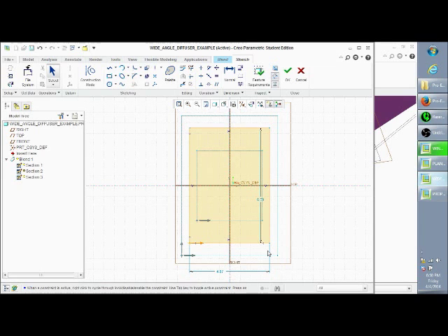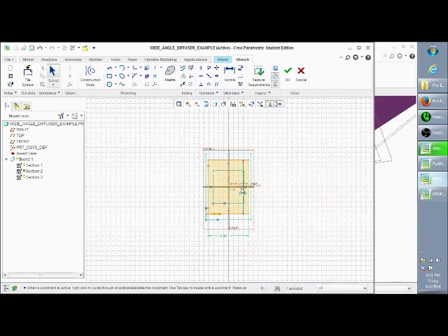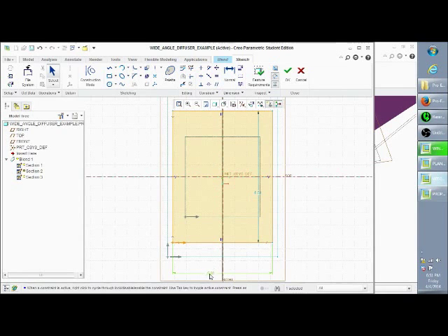I have not been able to get my symmetric constraints to appear for me. That's why when I created that first square, whereas here I'm using the symmetric constraints, I wasn't using it for the first one. They don't automatically set up. So I'm going to make this one 3.5 plus 1.5. Actually, no. Wrong side. 2.5 plus 1.5.